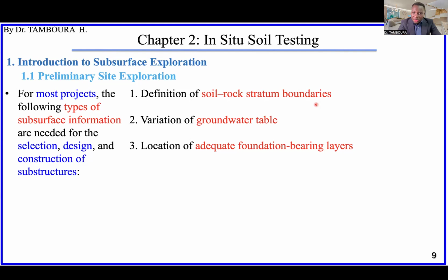As I said, sometimes you may have the bedrock near the surface, sometimes it's very deep, unreachable. You cannot reach it. However, by doing exploration, you can find at which depths we have higher bearing capacity of the soil. That means the adequate foundation bearing layer.